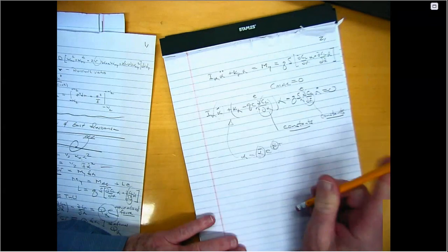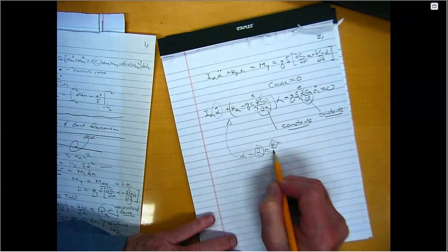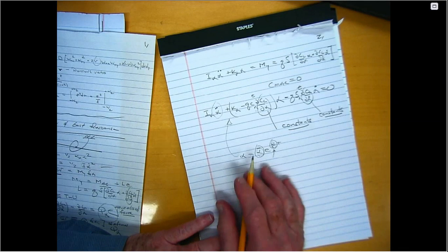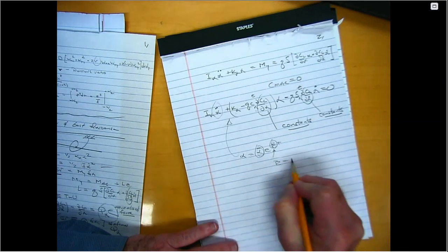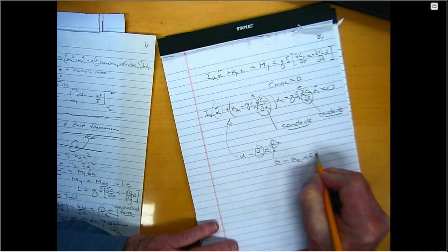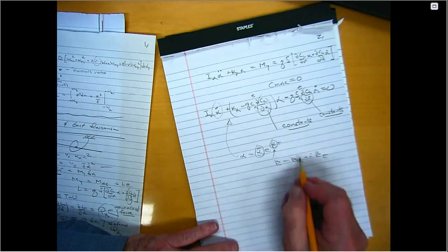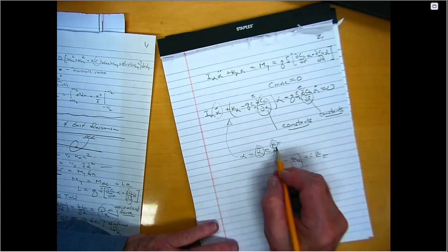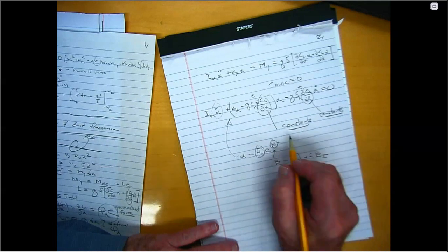But I don't really need even to do that to determine stability. To determine stability, all I need to do is examine beta. Beta in general will be a complex number with a real part and an imaginary part. It's the real part that tells me whether I'm stable or not. If the real part is positive, this is exponentially growing in time, an unstable system.